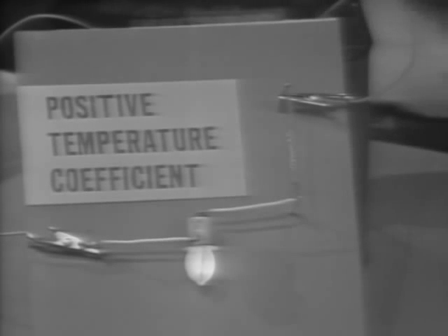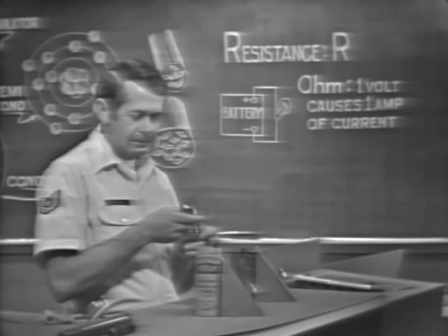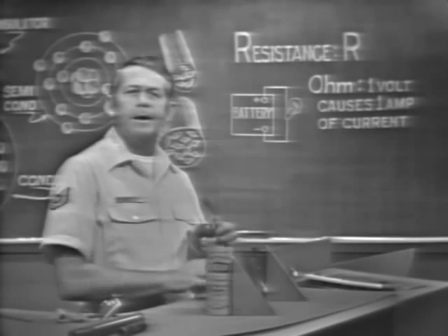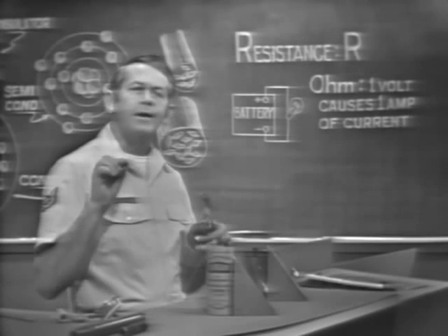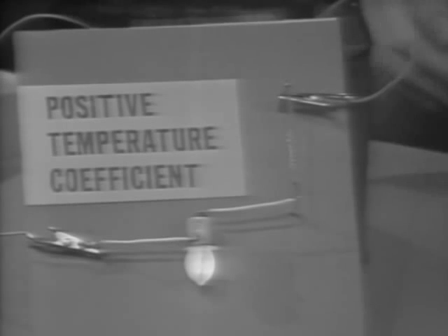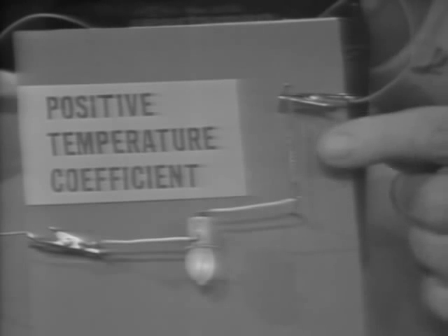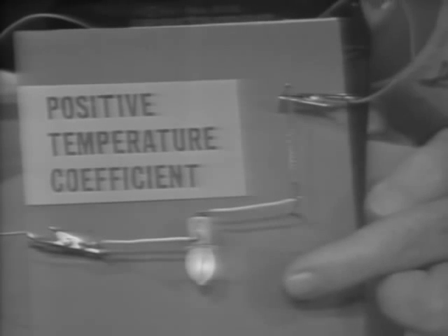Now to apply heat to the material, I'll use a small torch, so let me light it and set the flame so that it's just about right. Now, watch the intensity of the bulb as I heat the tungsten. Applying heat to it, notice that the bulb goes out. The resistance of the tungsten has gone up, which reduced the current through the bulb. Now, when I take the heat away and the tungsten starts to cool off, its resistance goes down because there's now current through the bulb.